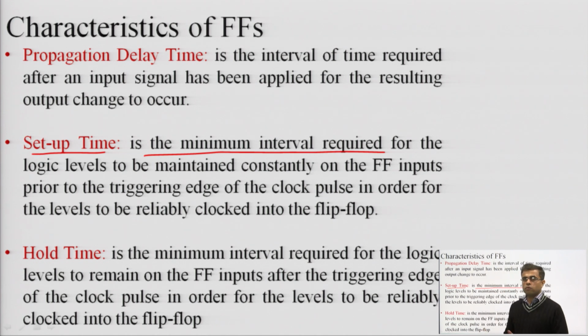So, whenever the clock comes, we also know that the clock's flip flops are edge triggered. So when these edges come, it should not happen that my flip flop input was applied and got removed and the flip flop clock's edge has not yet arrived. If my input has been applied and removed even before the clock edge arrives, then that input will go undetected.